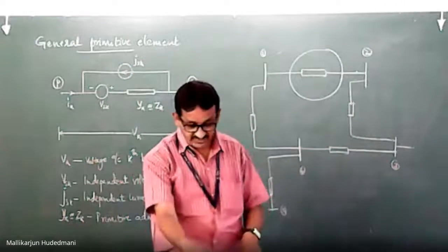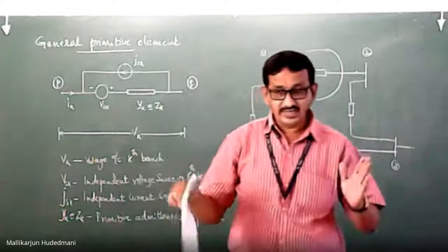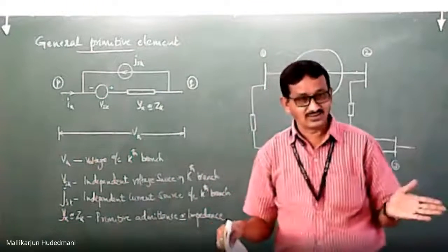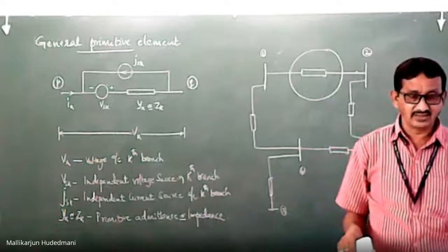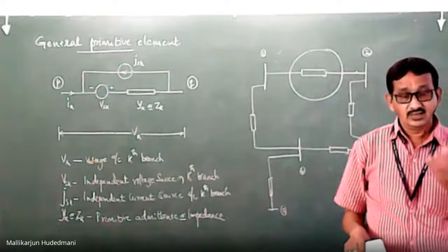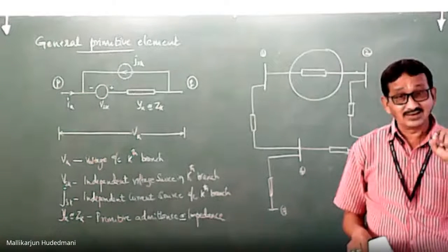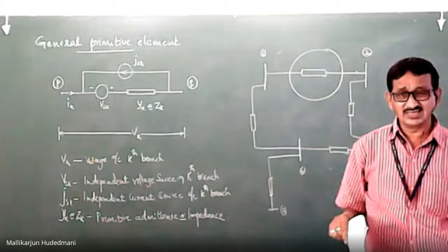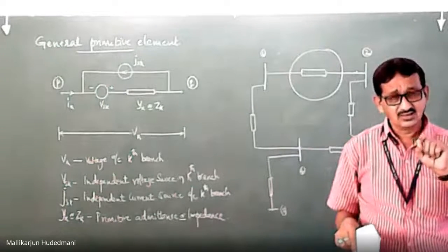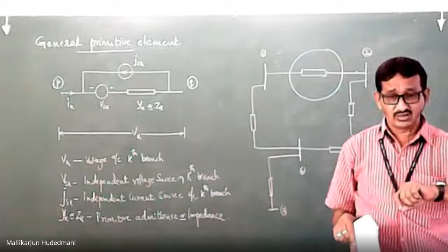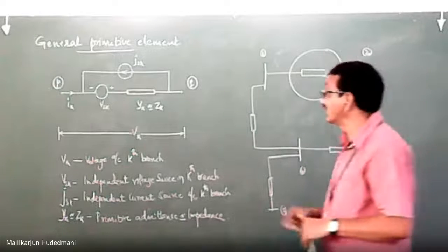When I was discussing just now, any element between bus 1 and 2 is a conducting material, and it possesses resistance and reactance. Then the primitive element is the unconnected state of representation. It is just a resistance and inductance, or resistance and reactance if I call it particularly, in the unconnected state.